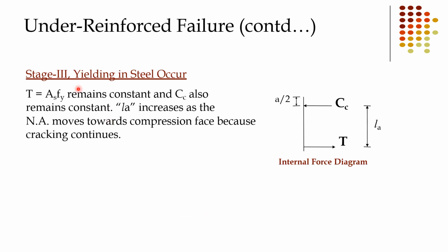Third stage, yielding in steel. Load keeps on increasing until steel starts yielding, and after yielding of steel, concrete crushes. T as Fy, the tensile force, remains constant and Cc also remains constant. La increases as the neutral axis moves towards the compression face because cracking continues. As cracking continues, the neutral axis starts moving upward. As a result, La will also increase.